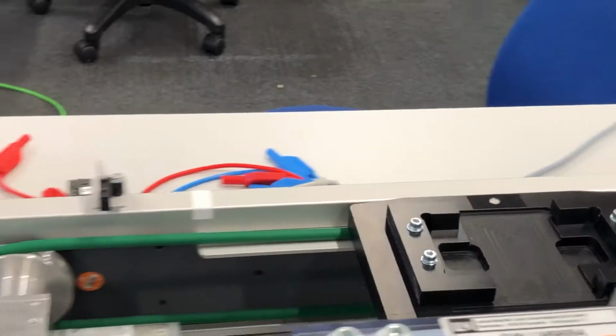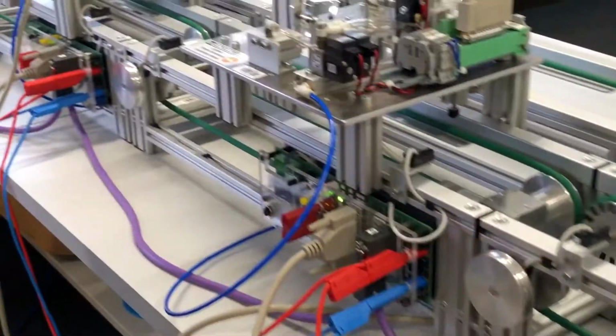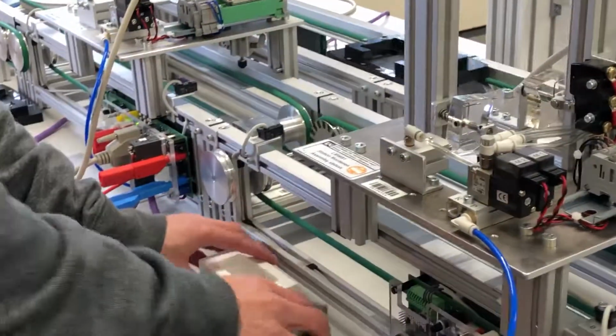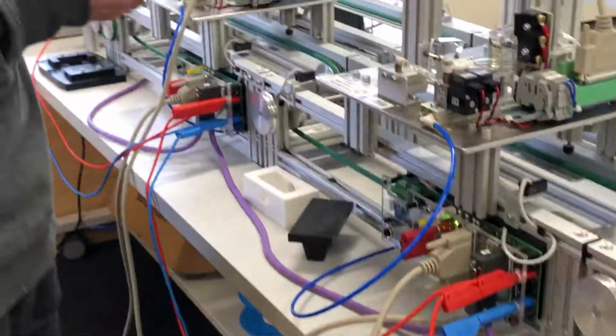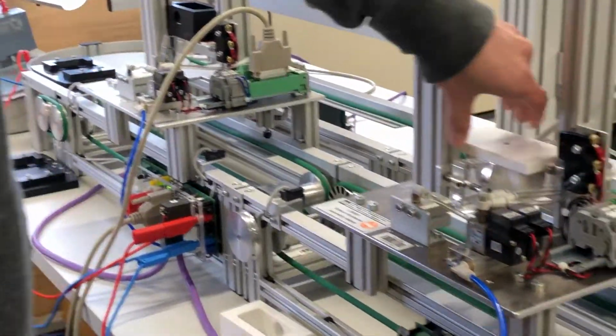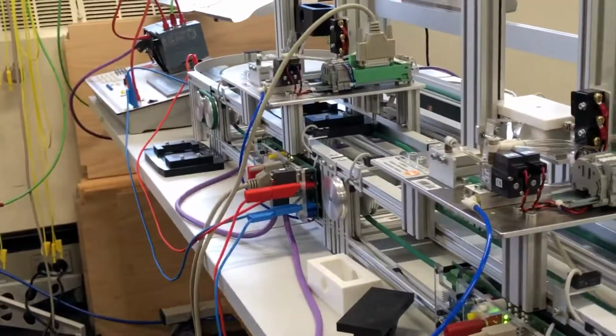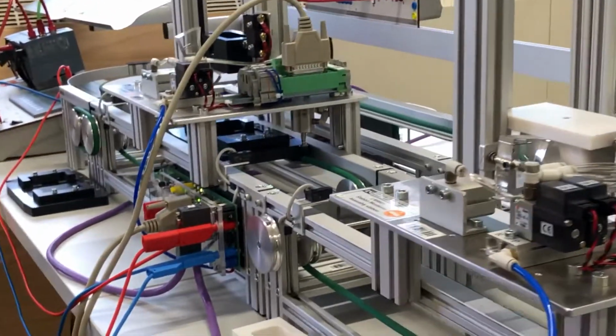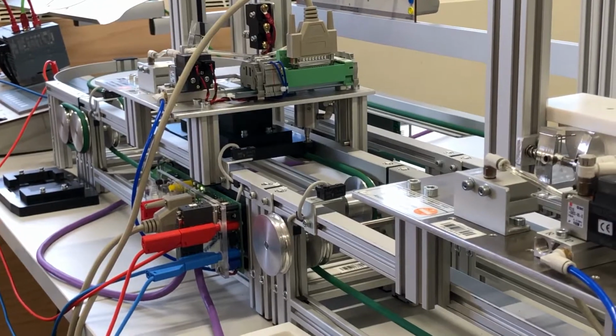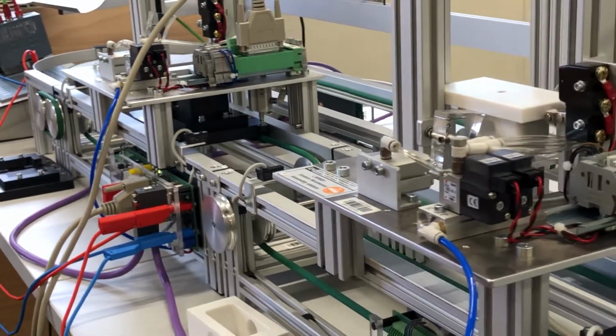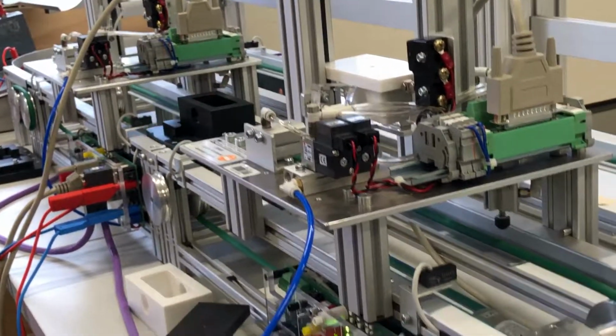And now I try to put a different color. So the manufacturing line should stop and reverse the wrong product back. For example, I want to put this black one, and the top one is white, a different color. So it means something is wrong with the manufacturing. When it comes to station 4 here, it should stop the whole manufacturing line and reverse it, so people can pick out the wrong one.